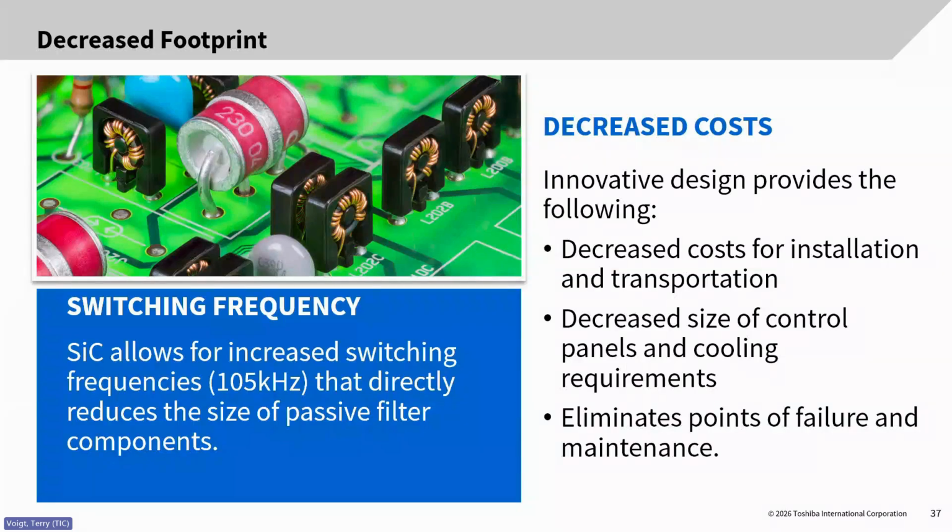Another big benefit to these components is that film capacitors are used. Instead of electrolytic capacitors inside of a normal VFD, which have a shelf life essentially, or need to be reconditioned after they sit idle, let's say about 2 years.